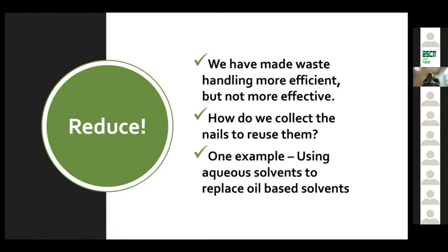We would take whole entire engines, generator sets, all of those things, bring them back and remanufacture them and send them out. But one of the problems we had was we were using oil-based solvents to do the cleaning, and we would clean all of the parts because you have to completely disassemble and then you have to clean, and the cleaning has to be done in a scrupulous way because you don't want any embedded particles left on the metal. You want the metal as clean as you can make it.